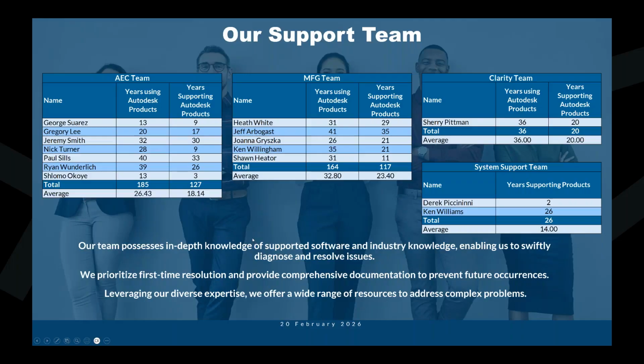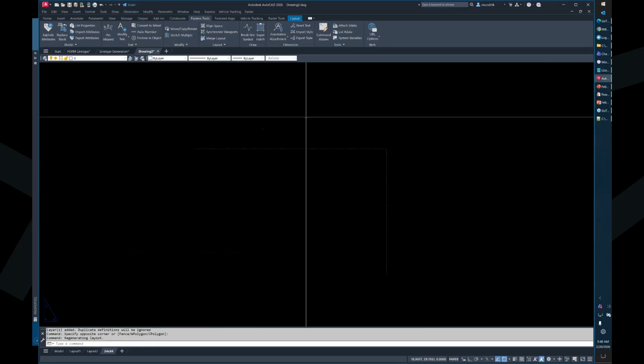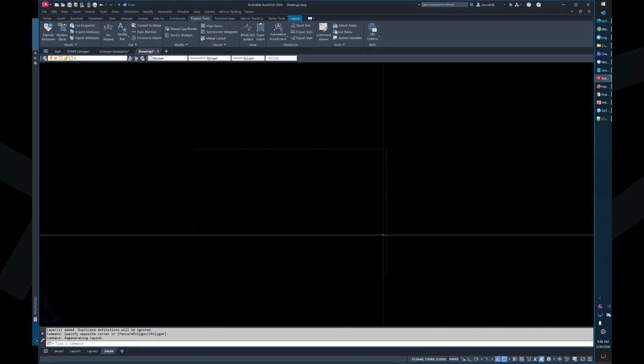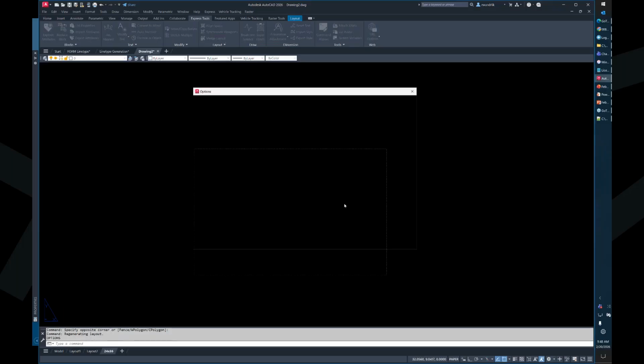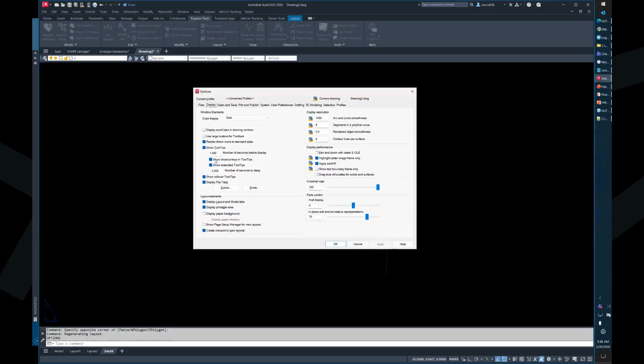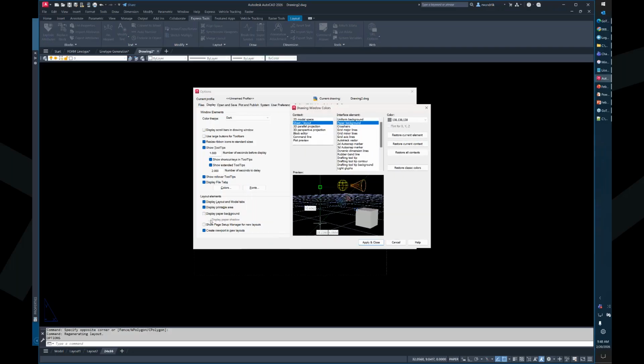Where do you set the colors? You're talking the background color? Because my layout tabs are black. Right, that's in options under display. You come down here to colors. So I go to sheet / layout and I change the uniform background to black. I turn off my paper background so I don't change that, and that paper background gets turned off here. I uncheck both of those.